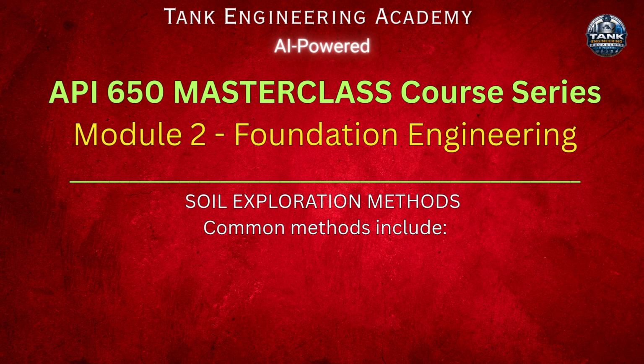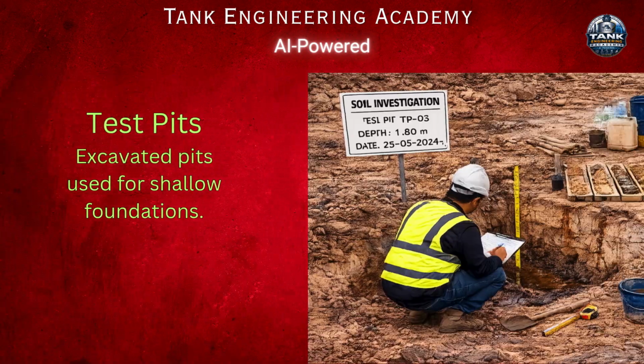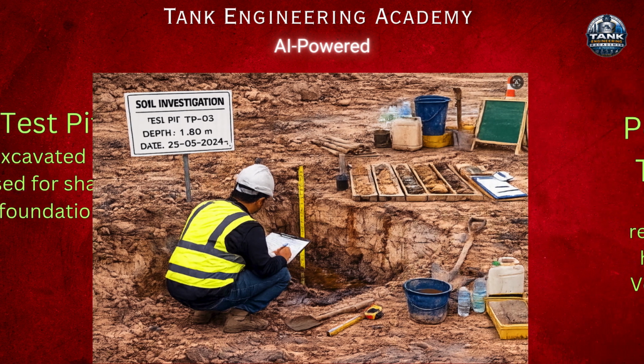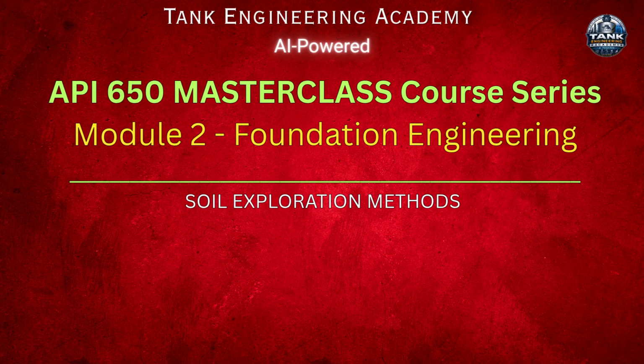Soil exploration methods. Common methods include boreholes, the most common investigation method. Engineers drill into the ground to collect soil samples. Test pits, excavated pits used for shallow foundations. Cone penetration test, CPT, measures soil resistance using a hydraulic cone, very effective for sandy soils.